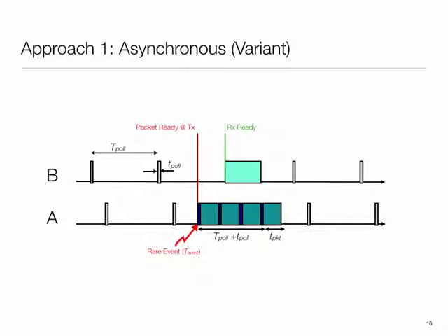So on average, you can save half the active energy. You can imagine these variants to this basic idea, with somewhat more complicated protocols, but they can save on the active side energy also. So that's one approach, with the caveat that you do need to make sure that the duty cycle period is accurately known on either side.